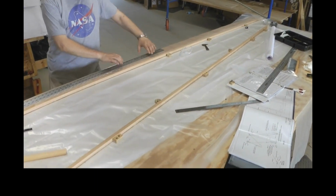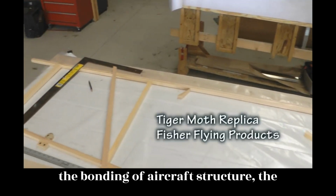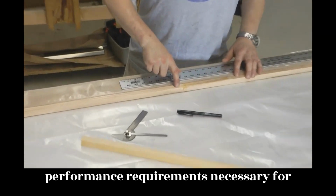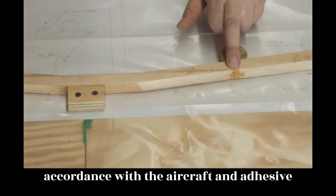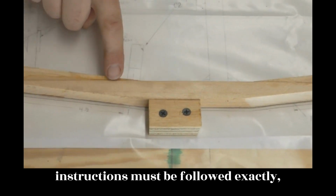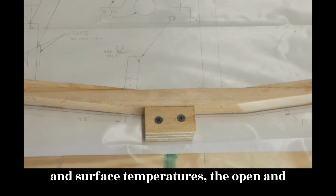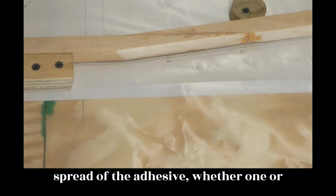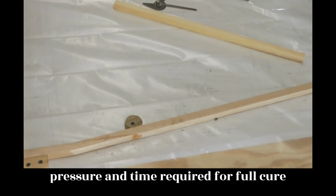Glues, adhesives. Because adhesives play a critical role in the bonding of aircraft structure, the mechanic must employ only those types of adhesives that meet all of the performance requirements necessary for use in certificated aircraft. The product must be used strictly in accordance with the aircraft and adhesive manufacturer's instructions. All instructions must be followed exactly, including the mixing ratios, the ambient and surface temperatures, the open and closed assembly times, the gap filling ability, or glue line thickness, the spread of the adhesive, whether one or two surfaces, and the amount of clamping pressure and time required for full cure of the adhesive.